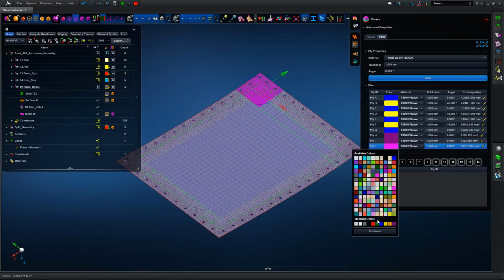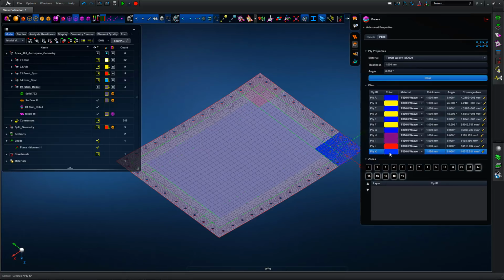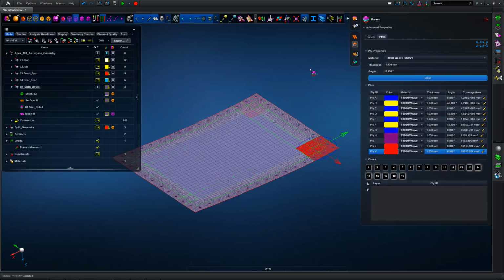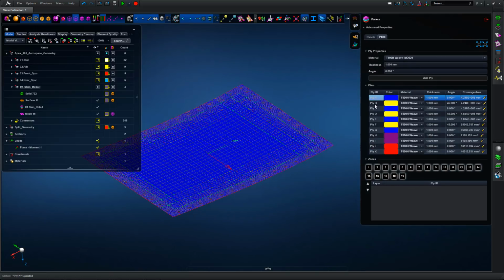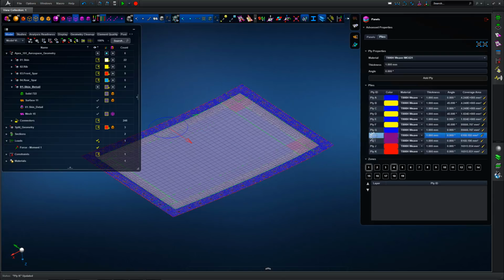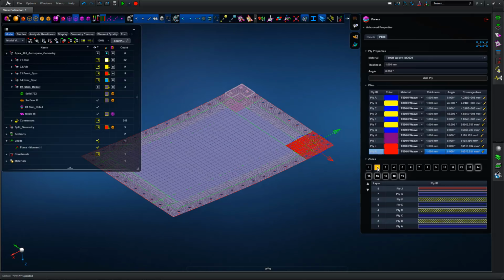And again, so creating a slightly bigger patch ply in the corners, and again same material, same thickness and a 0° orientation, and again updating the colour so we've got a good understanding of what we've done with the plies for later on. And again we've got the same plies defined from the original laminate, so we can just cycle through those to show the 7mm down to 5mm down to 3mm, but of course now we've got the 2 pairs of patch plies on the outer surfaces.